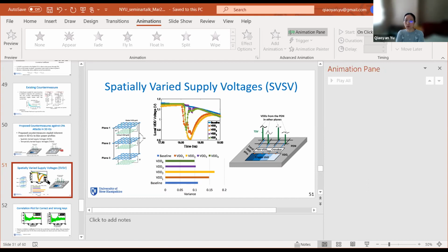Interposer wise, yes, we can do it, but it's not a vertical communication. So for the noise dissipation or heat dissipation from one tier to another tier, we couldn't find a good platform to perform our simulation or emulation. So that's why we mainly rely on transistor level simulation with practical PDN models in Cadence. So that's how we did it.